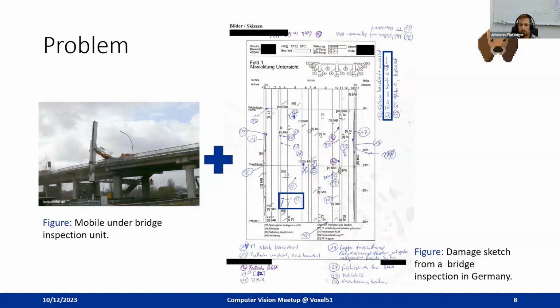Furthermore, the defect sketch is attached to the report in order to enable a visual comparison with other, especially consecutive, inspections. The defect sketch is the basis for tracking the defect development, but the problem is that the condition ratings, which are strongly based on the damage sketch, tend to diverge and are quite inconsistent.